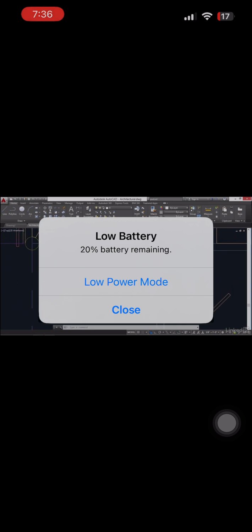So let's go ahead and rotate this chair, Enter, from the intersection point. So I'm going to hold down Shift, right-click, and choose Intersection, and click right here. So that's the base point of the rotation. And the rotation angle is something I don't know numerically, but I'm going to get AutoCAD to figure that out for me graphically, simply by snapping to this point down here.